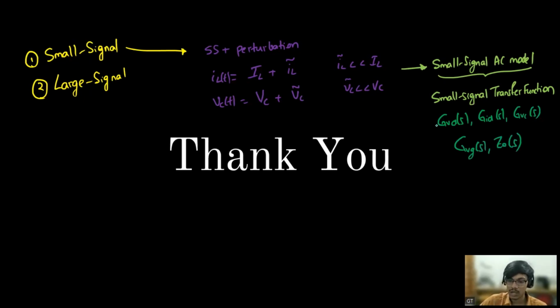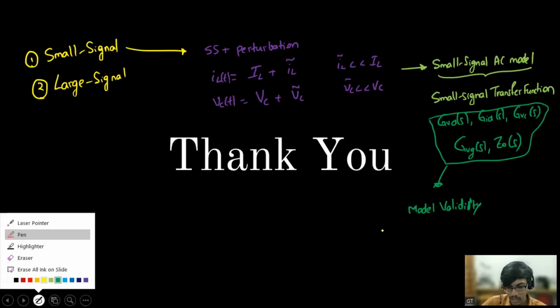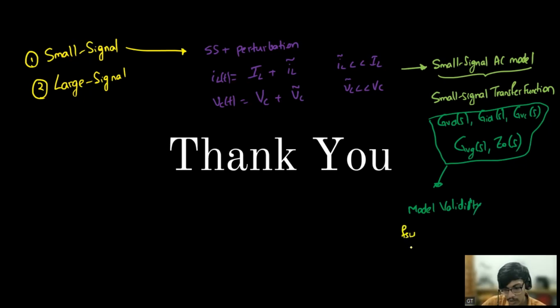All these are small signal transfer functions, which means they are only for very small perturbations, and they have limitations. They are based on some assumptions, so they have some model validity. These models are not always valid. The model is valid till FSW by 10 in the case of voltage mode control, and in current mode control we can go up to FSW by 8.